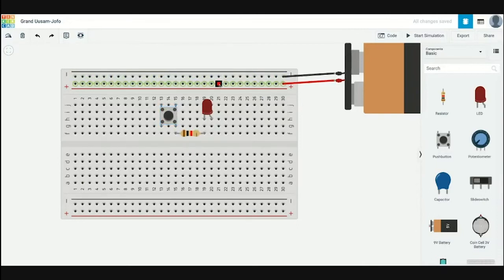We're now going to tap power from the power rail and take a wire and connect it to the anode of the LED. If you hover the wire over the 20 line terminal on the breadboard, you'll see that the socket will actually grab the wire.